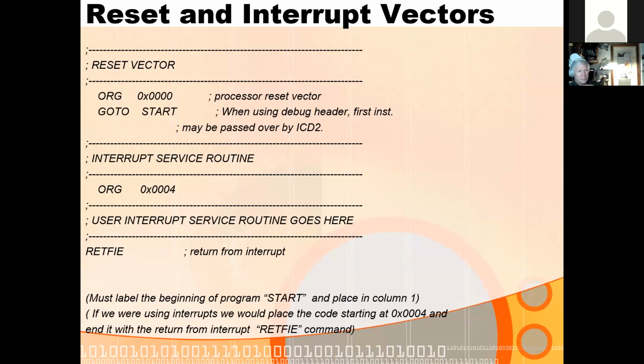Because you got to clear the pipeline from where you were at. That's right. Because that next instruction is already loaded in the pipeline. And so when you take the jump, you have to flush the pipeline and start the pipeline over again. And that costs you an instruction cycle. Now, why do our Intel chips and AMD chips not have that problem?